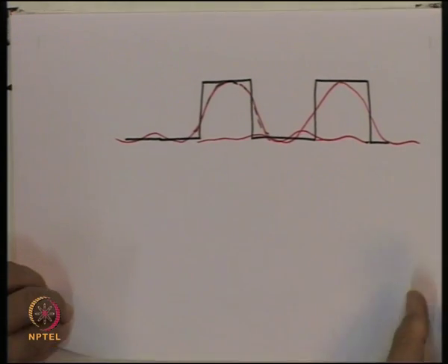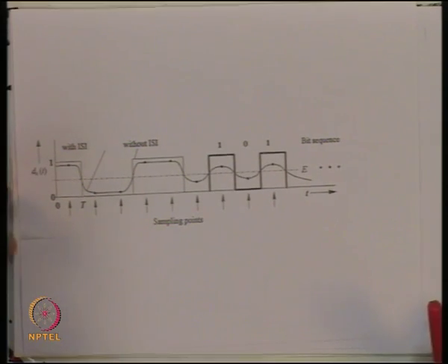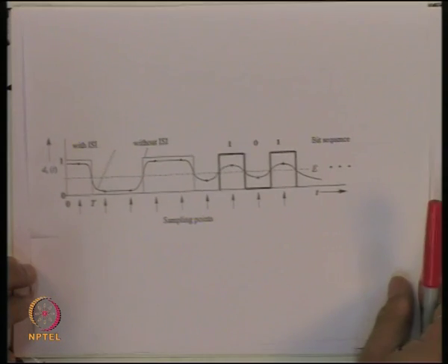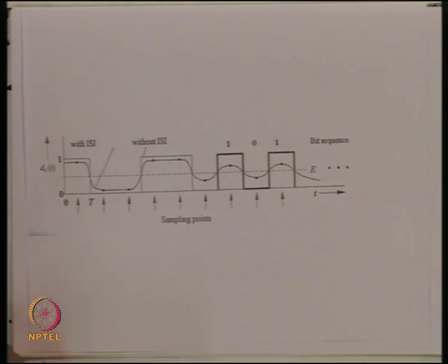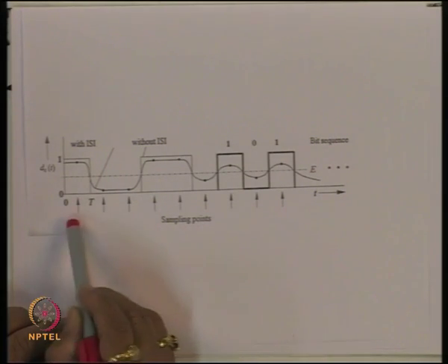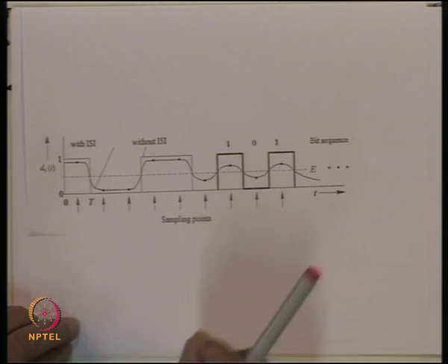So, when arbitrary data is transmitted, essentially we are having a situation which would look typically like that. And now what we are saying is, here we do not really integrate the optical power received inside a pulse. The pulses are converted into corresponding photocurrent and the corresponding voltages, and then you are having the duration or the location in time where we are expecting a bit.